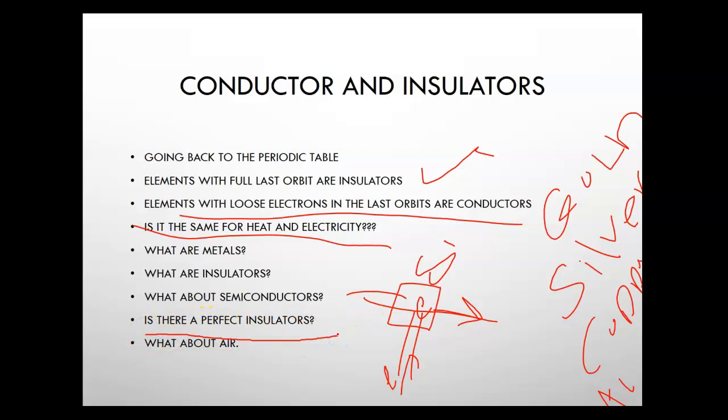Is there a perfect insulator? That's an important question. Is there a material completely insulated? No. Every material can conduct at the right voltage. Even rubber, even thick insulators, they're always rated. So do not feel very safe touching a high voltage wire with a glove thinking that it will be okay and it's not going to conduct.